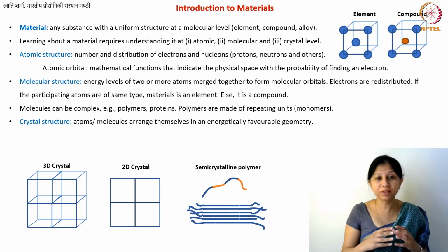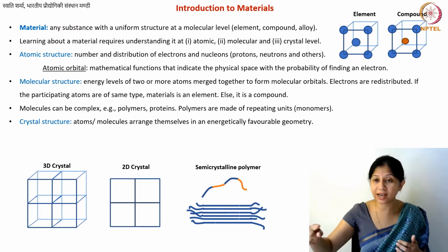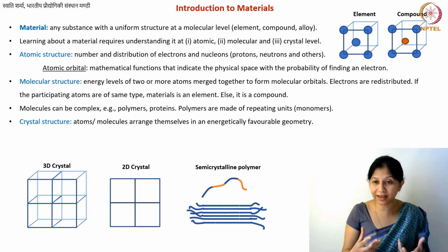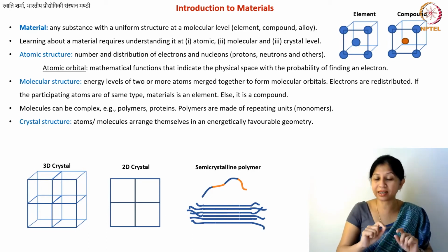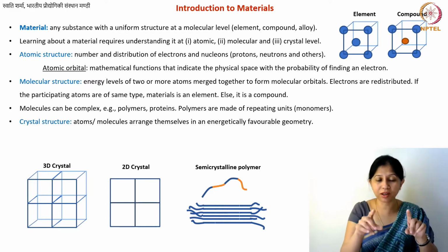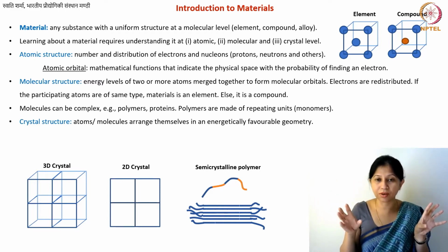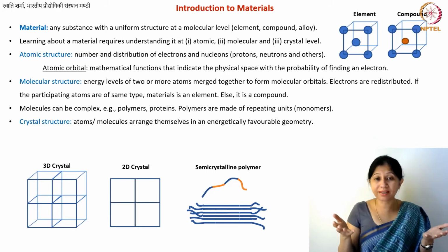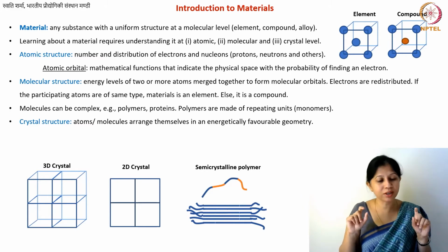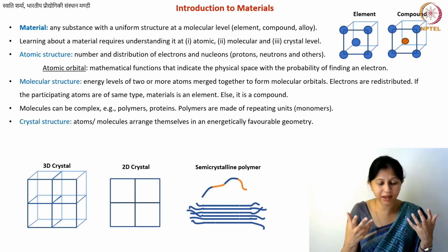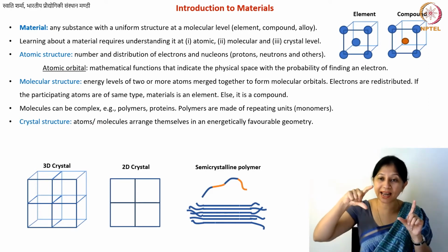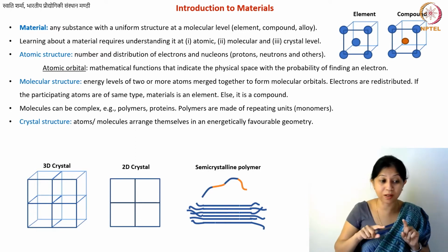Something called semicrystal. So you have polymers. This is an example. You know about polymers. You know that they contain these chain-like structures. Some polymers may contain sheet-like structures as well. And here and there, occasionally, some part of them has a certain type of arrangement, a layered arrangement, let's say. But on both sides of the crystal geometry I have made, both sides are random. So certain parts in the material will have this crystal structure or certain arrangement, and these little parts where you have the arrangement, you will call crystallites.